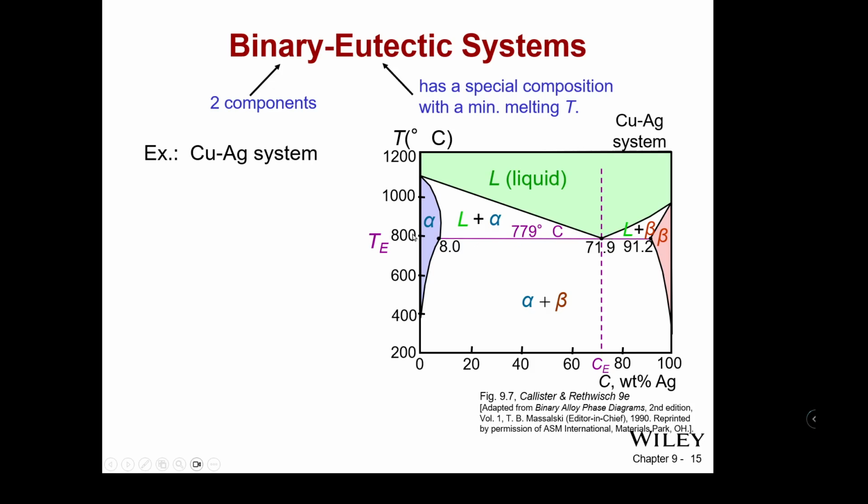So the difference between 800 C and 1100 C is a lot in terms of energy, therefore processing expense in order to work the material. So there's an appeal to being able to use something at a eutectic point. The downside is it is a weaker material than something of, for instance, a different percentage.